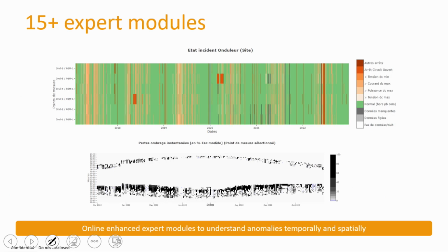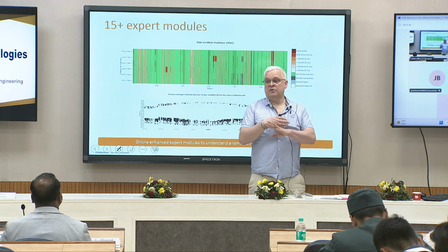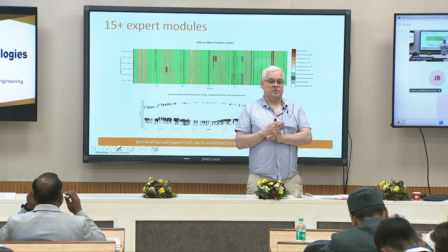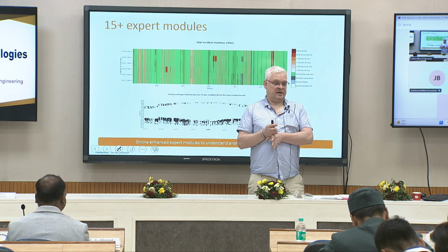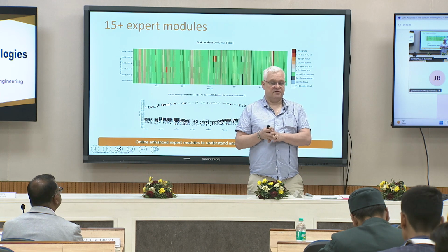I don't know if you have seen that I showed you a carpet plot one day on a facade. We are using a lot of that carpet plot to treat the data because sometimes if the inverter is not able to track the maximum power, there will be a lack of data, okay? But that doesn't mean that there is a problem.